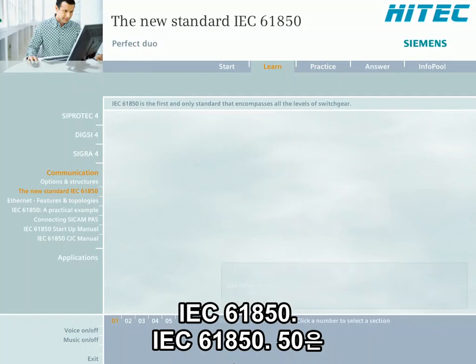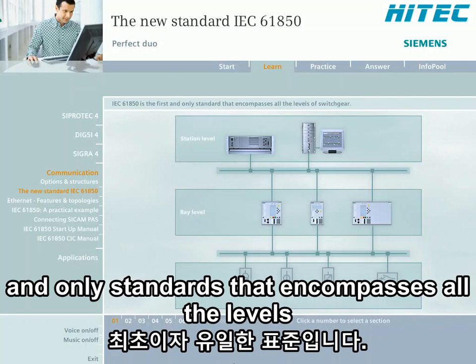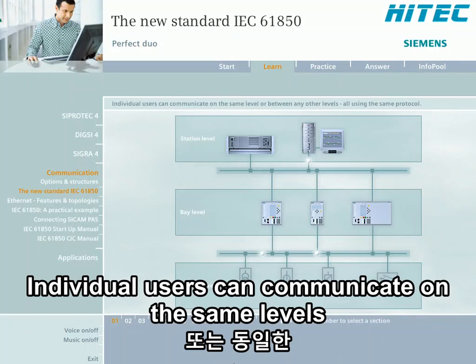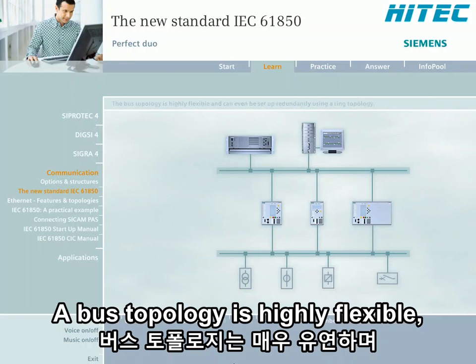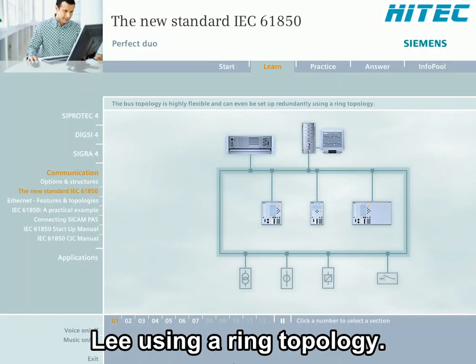IEC 61850 is the first and only standard that encompasses all the levels of switchgear. Individual users can communicate on the same level or between any other levels, all using the same protocol. The bus topology is highly flexible and can even be set up redundantly using a ring topology.